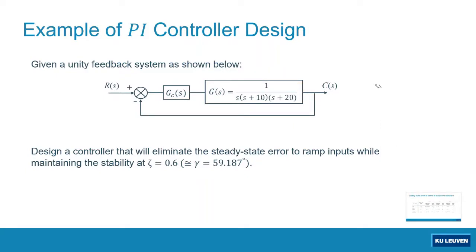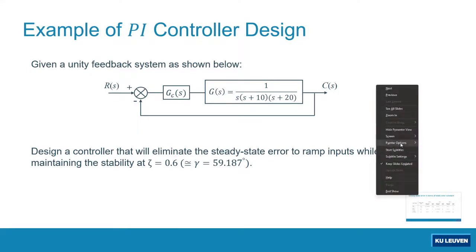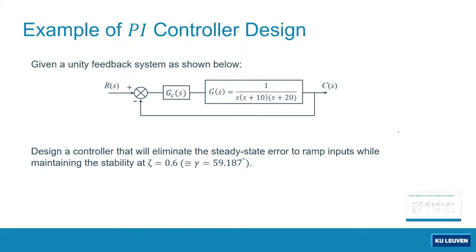Obviously, if you have a system that looks like this, the open loop transfer function G(s) has only one pole that is equal to 0. For the time being we haven't tuned the controller, so let's just consider Gc a proportional controller with a constant gain of 1.